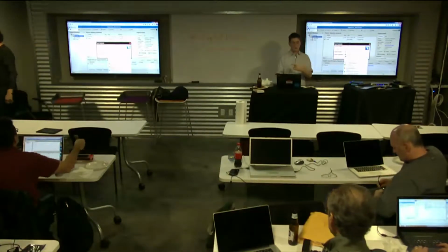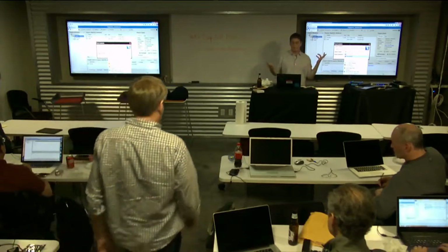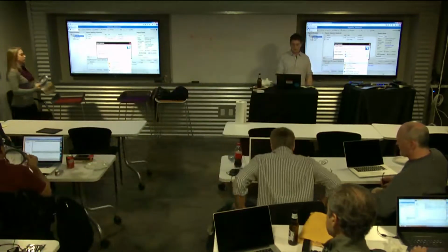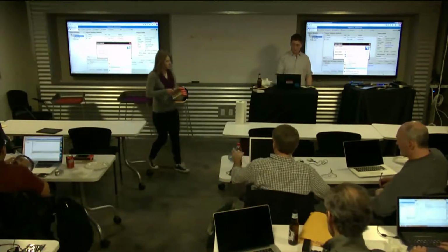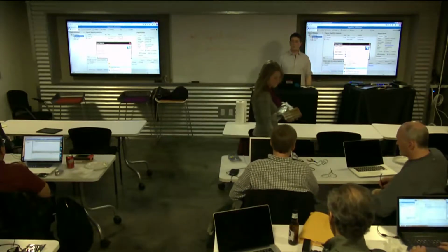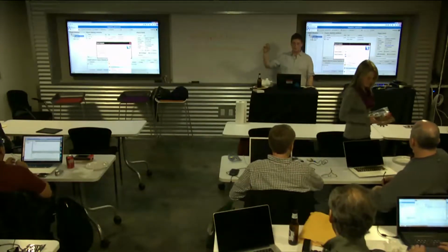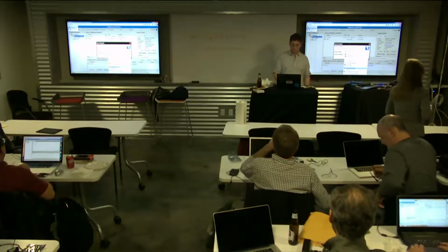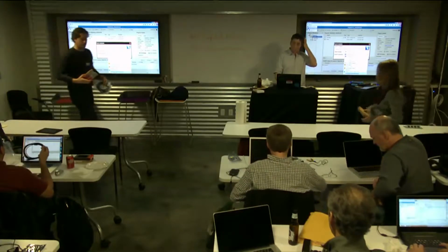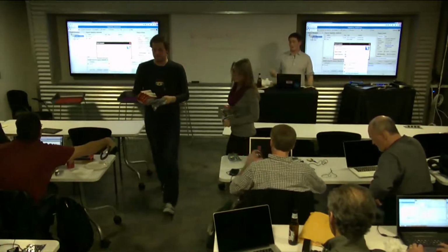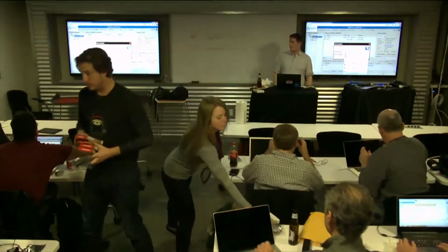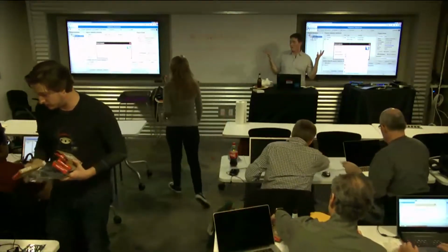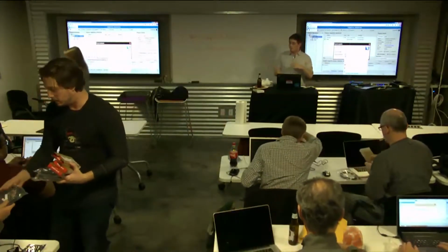And then I select the toolchain I want. In this case, Keil, because I like Keil. You can also do GCC or IAR. There's Kinetis because it's a Freescale MCU, and Kinetis is Freescale software tools. There's also just a straight zip archive. If you just want the code itself, you can just grab the zip. This is a great way to get different project files for different compilers.